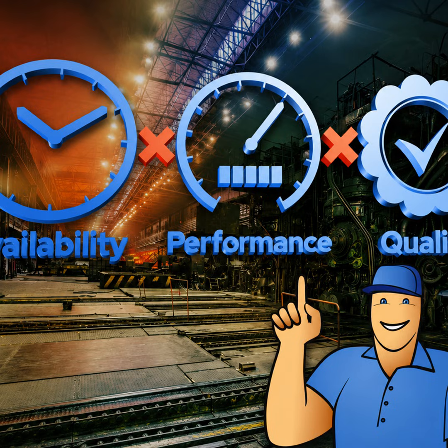Putting it together, the OEE calculation. Now it's time to put the pieces together and calculate OEE. OEE equals availability times performance times quality. In this example, that means 81.6% times 87.7% times 96.1% equals 68.8% OEE.